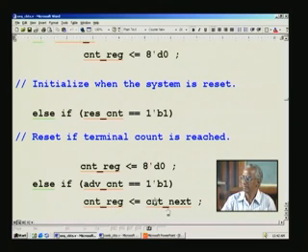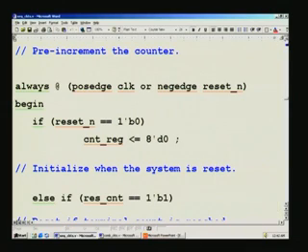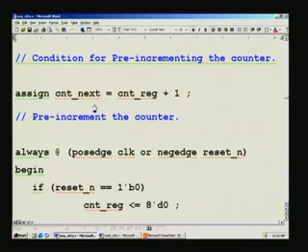You may think, is it not going beyond the time? It will not, because whatever is pre-computed here again depends upon this register only. So it will not keep on incrementing, because although it is assigned in an assign statement, which is a combinational thing, right, it depends upon the counter register. So it will change only with the arrival of the positive edge of the clock. You can rest assured that this also will change only subsequent to the arrival of the positive edge clock.